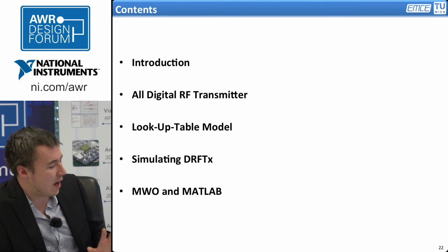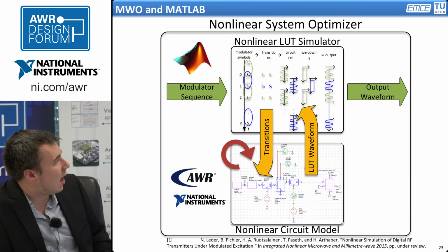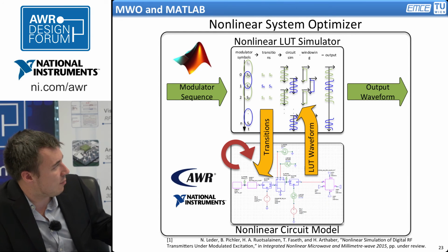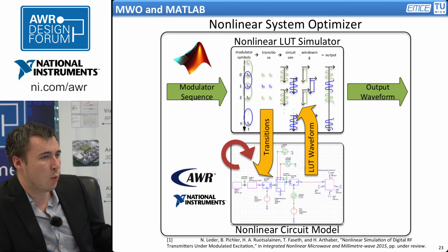So this is the way I set up the simulation, and now we want to take it one step further and really incorporate it into this simulation cycle, since this has the additional advantage that when we run this MATLAB AWR simulation cycle as many times as we need to fill up our database, we can then simulate any arbitrary kind of modulation sequence just by having this database.